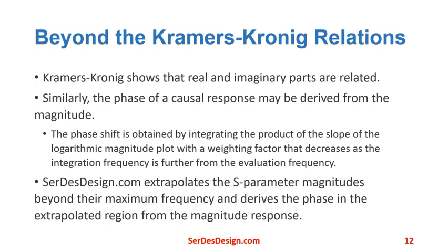Such a relationship shows that the phase shift is obtained by integrating the product of the slope of the logarithmic magnitude plot with a weighting factor that decreases as the integration frequency is further from the evaluation frequency. SerDesDesign.com extrapolates the S-parameter magnitude beyond their maximum frequency and derives the phase in the extrapolated region from the magnitude response.